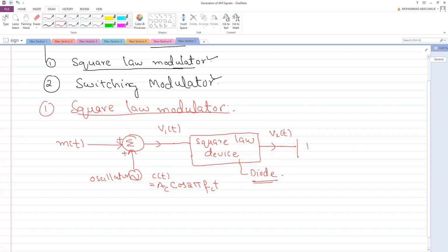Then this will be passed to a band pass filter. It's not low pass, it's not high pass, it's band pass. A band pass filter just passes a band of frequencies, f1 to f2, a range of frequencies that will pass through it. It depends upon the f1 value, and f2 depends upon its range. So ultimately you will get your value, that's s_AM(t), your amplitude modulated signal.